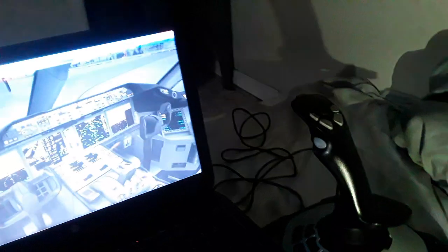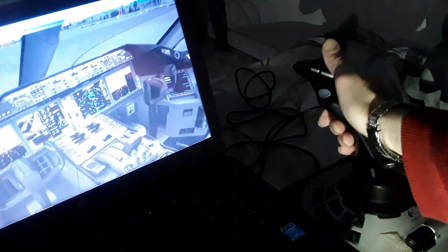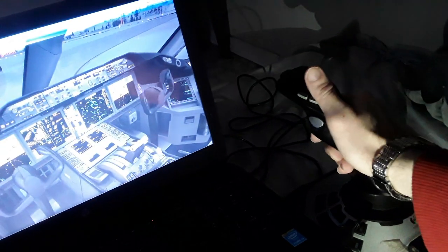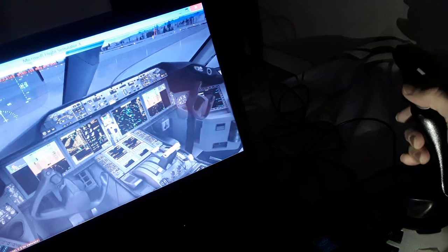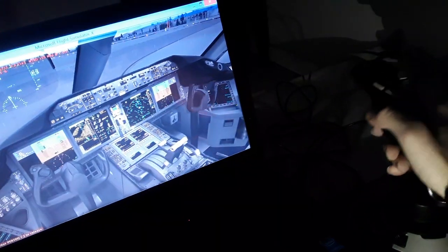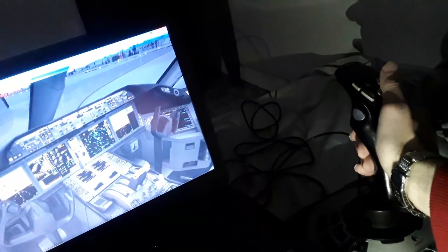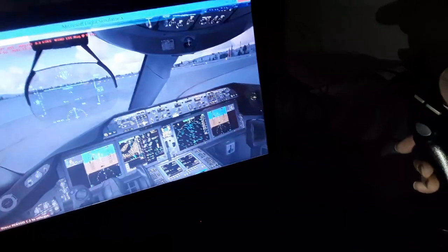Also, as you can see, both the captain and the first officer are moving together, or they're interconnected in flight. Unless you have a failure, you have an override mechanism for either side. So in the Airbus you have the side stick priority anyway in the left and the right side. So flight controls interconnected.